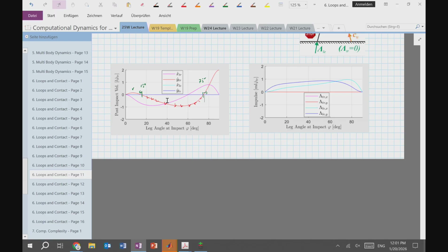You look puzzled. You don't believe me? What is the formula for friction in that case? How large is the force in there? Well, normally you say tangential force is mu times normal force, but for mu being infinity, that's kind of weird. So I could just write this as 1 over mu times Ft equals Fn. And then this is anything divided by infinity, so this is going to be 0. So I'm just saying there's no normal force, but you still get a tangential force. That's weird, but this is what infinite friction means.